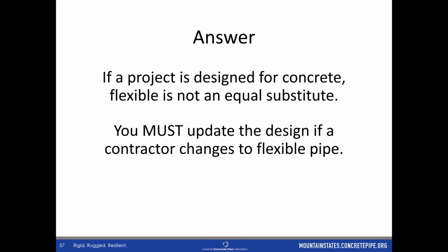The other concern that we need to take into account as design engineers is, can I swap it out for a flexible pipe in that North Shore project, as we mentioned earlier, that had high groundwater and issues? Probably not a good option, right? To use a lightweight flexible pipe that is a liner that could potentially float on us and give us problems when the groundwater is high. We don't want to see pipe heaving our road and causing problems down the road for the next person to have to fix. So we've got to be smart about all of these things. So it depends. I would say that's the best answer there.